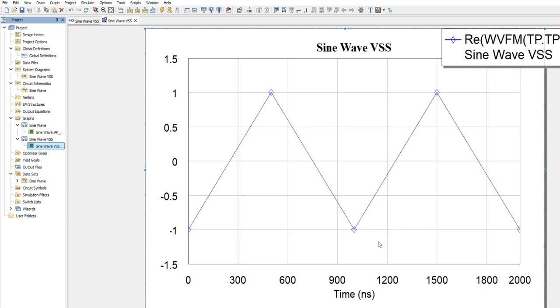VSS does not interpolate between samples. It simply joins 2 consecutive points with a straight segment. Conveniently, those samples happen to be aligned with the maxima and minima of our sine wave, so we are kind of getting the amplitude of the sine wave right. But that's just a bit of luck.